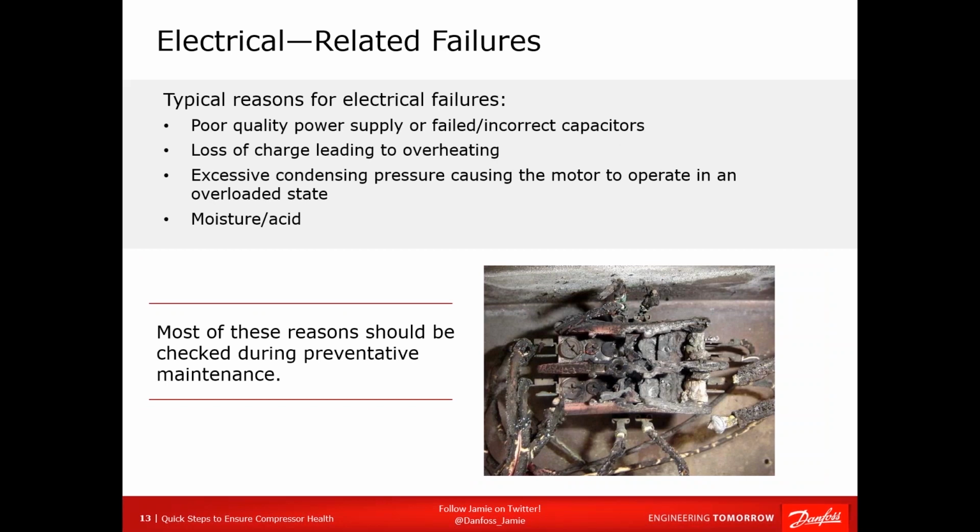So what are some of the primary causes of electrical failure? Well, the easier ones to catch are poor power quality. So if you're supposed to have 240 volts and you have 180, that's a problem. If you have three-phase power and you have a huge voltage imbalance between them, that's also a problem.